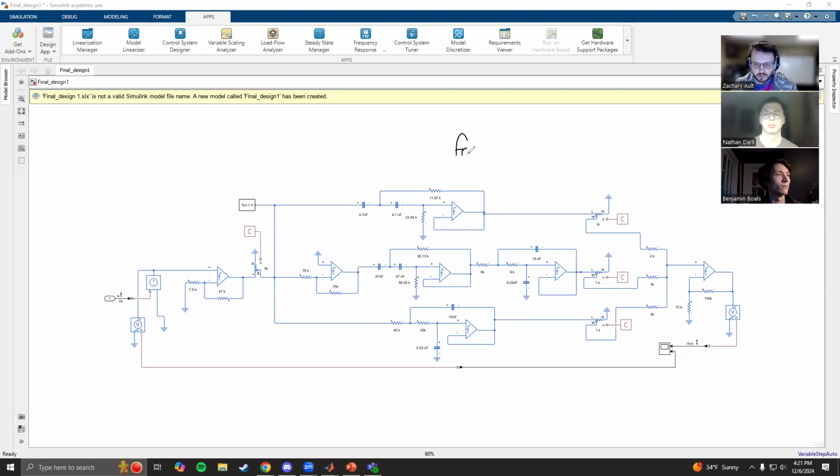And so with that, we were able to use our cutoff frequency equation, so FC equals 1 over 2 pi RC, and then we could solve for our values of R. And you can see that these two values of R are not the same. That's because each one of them is based off of this R value. So our top resistor is our R value times 0.707, while our bottom resistor is that R value multiplied by 1.414. And then once the signal goes through this filtering stage, it will then be passed on for later analysis.